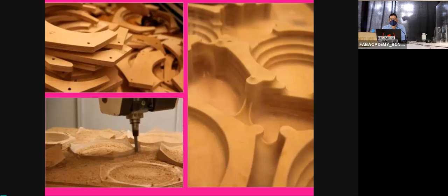With this technology, we can produce really simple 2D cuts, something you could also find in laser cutting, but with thicker materials, or you can produce complex 3D models with really smooth finishes. Compared to a 3D printer, you will ask, why would you use a CNC milling machine? First, the materials that you can process with the machine are completely different. For example, nowadays you can 3D print stainless steel or aluminum, but the accuracy and surface finish of the models that you produce with a 3D printer are rough. They don't have really high tolerances.